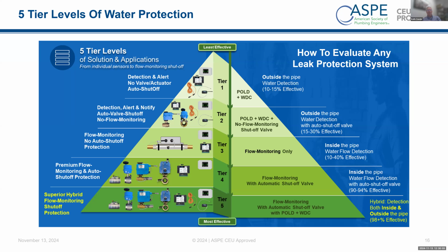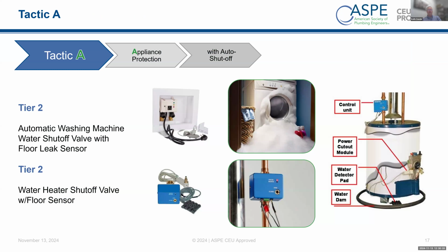That's the big caveat. If you test, if you make sure it's still working, if you make sure the customer did not turn the valve off on manual when the electricity went off and stick it back on the auto, make sure that they didn't unplug the plugs when they were trying to clear the alarm because they didn't know what buttons to push. You just have to go in every quarter, every 6 months, every 3, once a year, twice a year, test it, make sure it's all working, or you're going to get caught without that perfect plan.